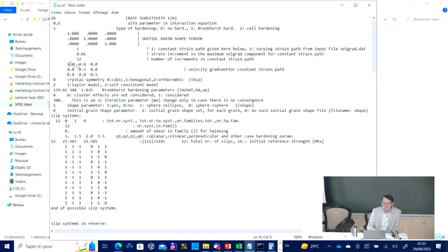In elasticity, there can be volume change. In plasticity, there is no volume change, so then the diagonal is 0. There are no shear components in tensile testing, if you do it right. Because if you pull and the axis is moving in one direction, you will have shear components.